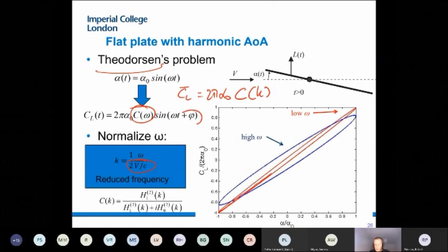And then it will be moving down when you start looking at amplitude delays. So what unsteady aerodynamics actually produces is moving from this straight line between lift and alpha to these ellipses with lower slope when you have harmonic motions.